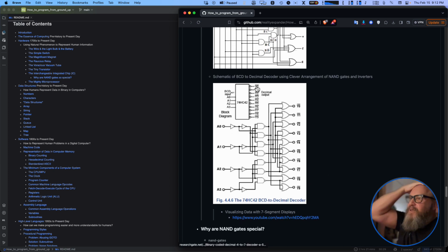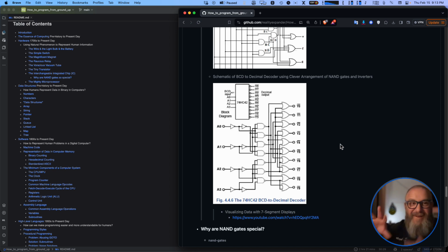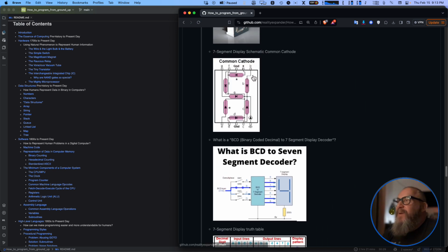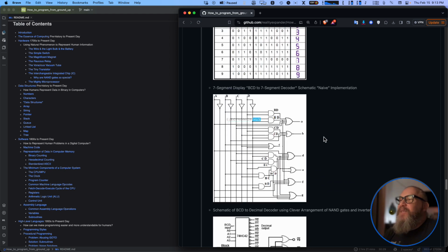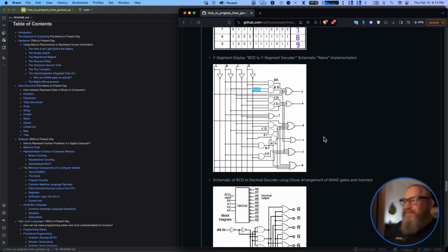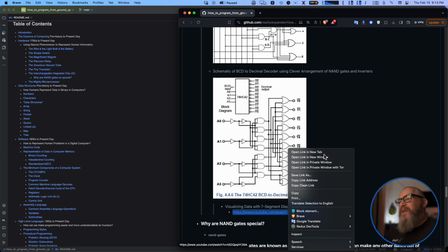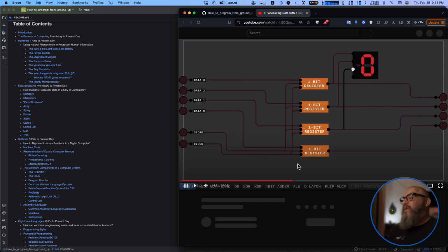And the output is low here. The reason it's low is because other equipment that has the cathode here, this common cathode, expects it to be low to be on. So that's what that means. And the negative means that normally when it's active, it means when it's low, it means that it's the digit 1. So that's all this terminology and notation. You have to know some of this stuff. I'm giving you this because most of this stuff messed me up.